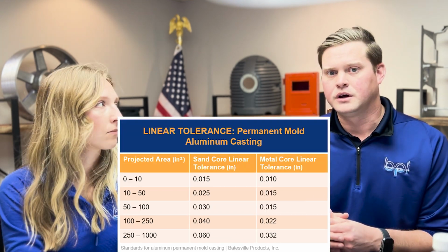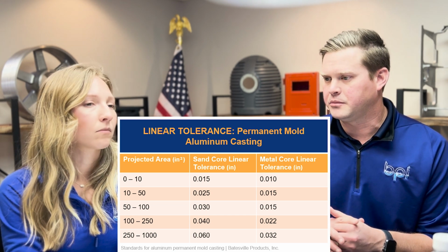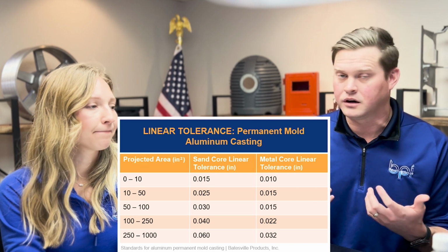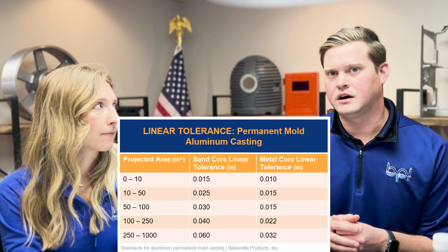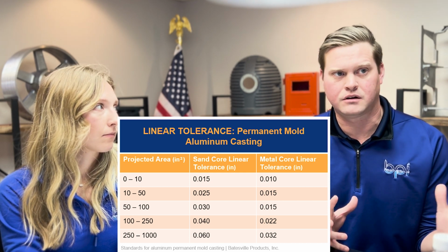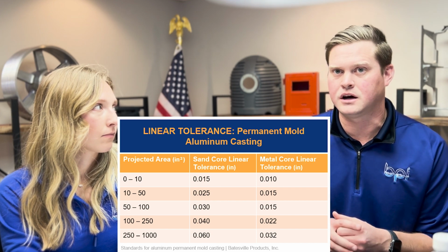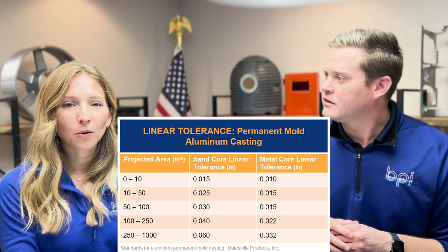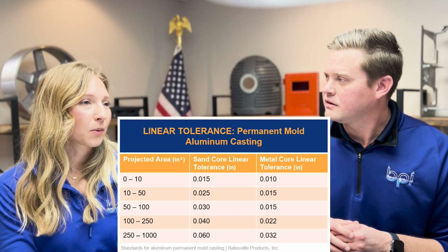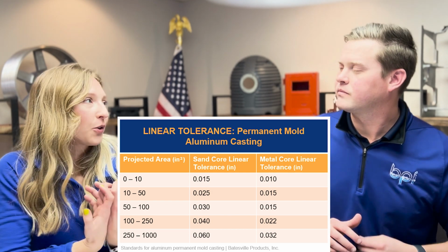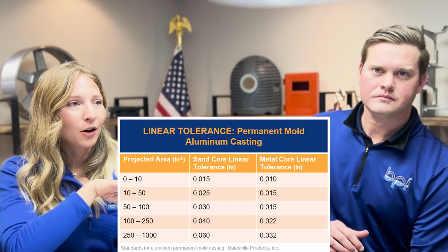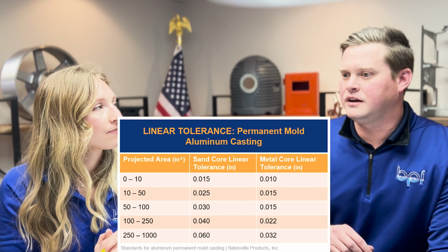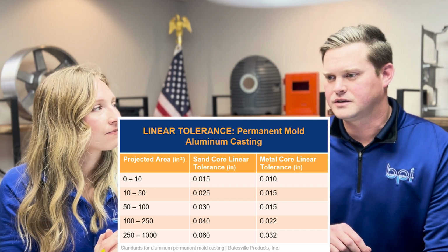Absolutely. A little bit further on, we talk about what we call semi-permanent mold casting, where you can cast in a sand core and have it shaken out, or you can have a different type of metal insert. A lot of times you'll see those sand cores when you have an internal cavity, almost a U-shaped part. Yeah, and it's used in a lot of different applications.